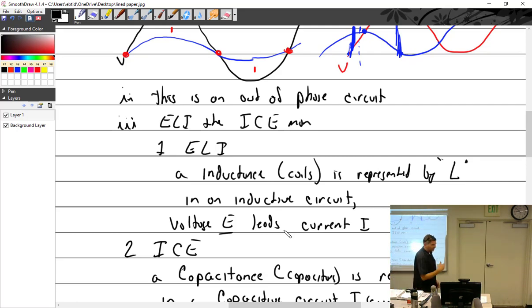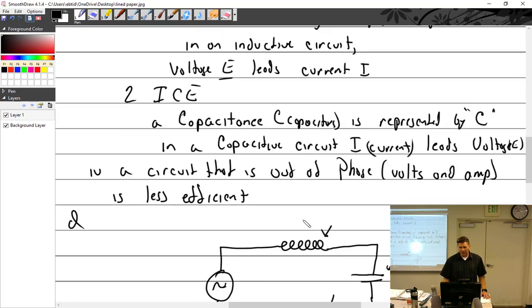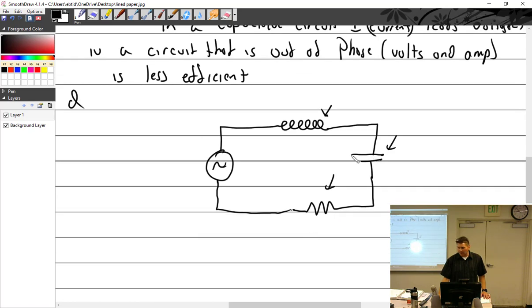So you see the electrons, the current is always leading the voltage, which is just on a timer. They don't cross that plate, they just go back. They can't. The plates don't touch. So they're always going back and forth. Well, again, I'll tell you this, which is going to come up later: in a DC circuit, we've said that's an open, but in an AC circuit, it's not an open because of the way the current's always going back and forth. Kind of, if you will, the plate fills up this way, then it fills up the other way, then it fills up this way, so it's allowed to go back and forth. It's simplifying it, but it does. In an AC circuit, it's not an open.